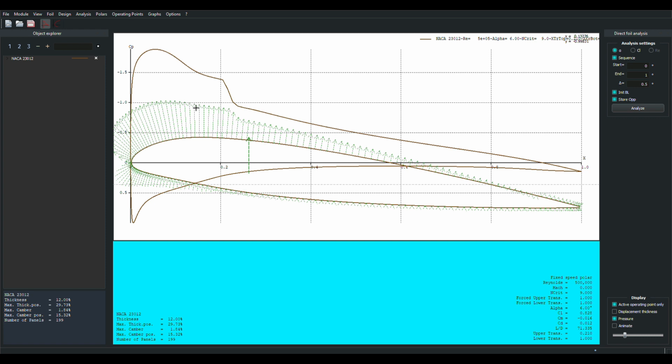Anytime that we're going from low pressure to high pressure, back here at the trailing edge, that is an adverse pressure gradient. Where we're going from high pressure to low pressure up here on the leading edge, that is a proverse pressure gradient. And we name them that way for a reason, because as the poor little air molecules get shoved over this airfoil, we get them accelerated here in the front.